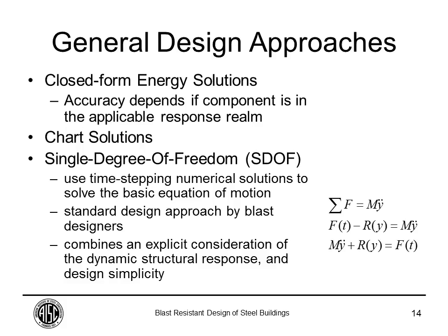Next, we have the single degree of freedom approach, which is the most typically used design method, at least in my experience. That is because it's a good combination of explicit consideration of dynamic effects, plus it's simple enough that it allows rapid design so that you can keep up with the design phases. We need to keep in mind that when we're doing a blast-resistant design, a lot of times you're part of a design team, and maybe you're in a design-build effort, which is very fast, so you have to be able to produce rapid and efficient designs so that you keep up with the design team. Single degree of freedom analysis gives you the capability of providing that balance between accurate designs and quick ones.